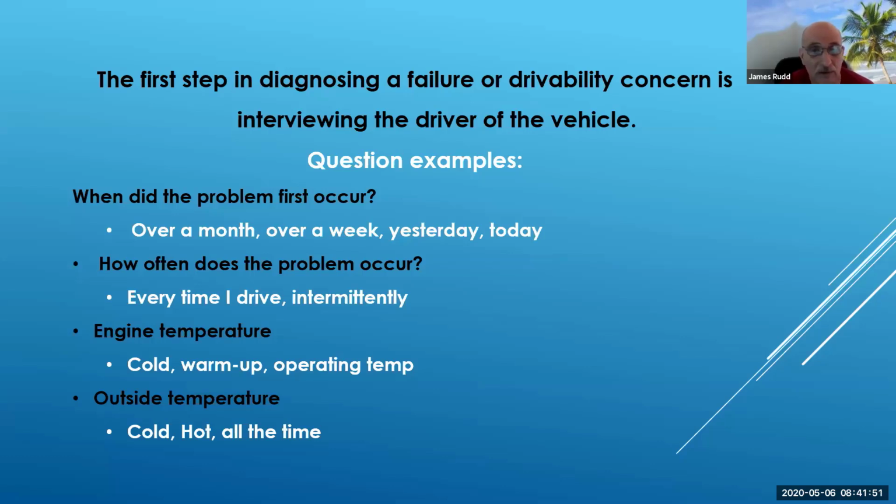So these things just kind of rush through my head when customers start saying, yeah, it only does it when it's first warming up. Oh, there goes the coolant sensor in my head. Or actually, the imbalance between the coolant sensor and the actual air charge sensor. So now these things pop in and you can start getting an idea of what the problem might be. And that led into the outside temperature.